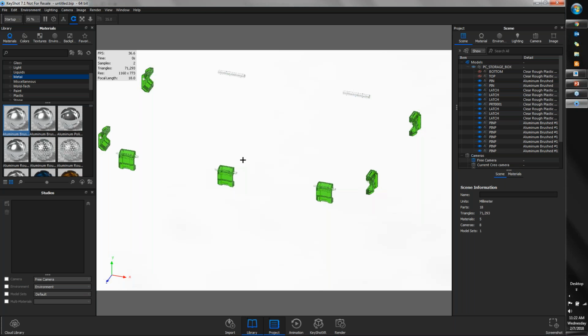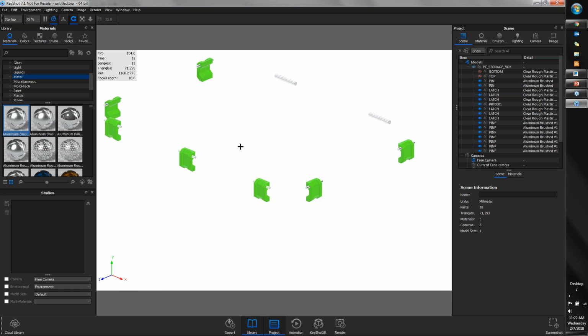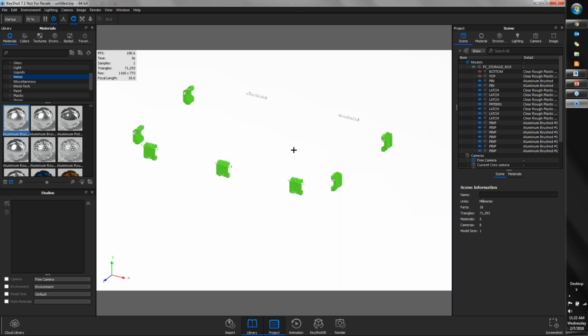This can really cause a strain on our CPU. So if we would like to turn that off or decrease that requirement for our CPU while we apply materials, we can always enable performance mode. And you can see that's going to get rid of shadows, it's going to get rid of reflections and decrease that rendering quality while we go through the rest of our workflow.